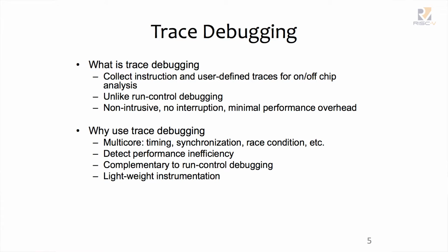You can generate the traces. You can extract the instruction trace from your real FPGA run. It's kind of non-intrusive, with minimum performance overhead. What it does is actually extract the instruction sequence from your processor, filter it, and only extract the information that is enough for you to generate the whole trace offline.